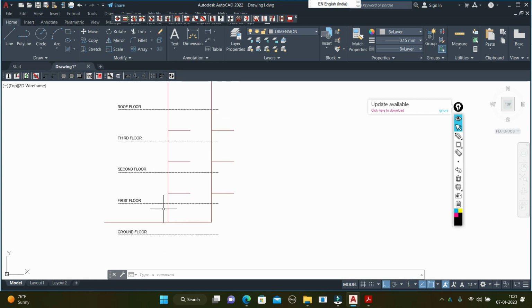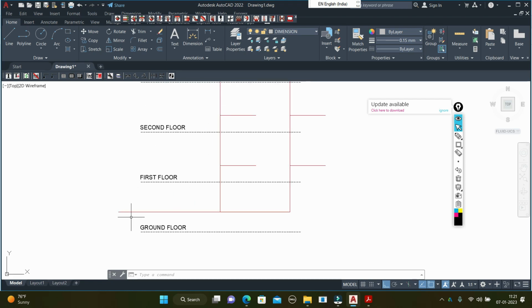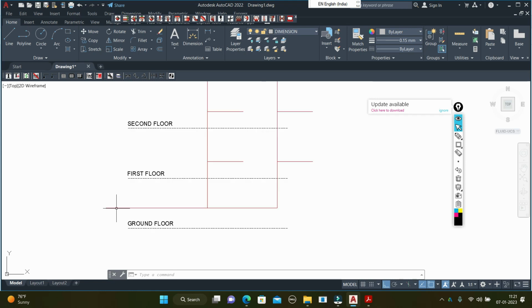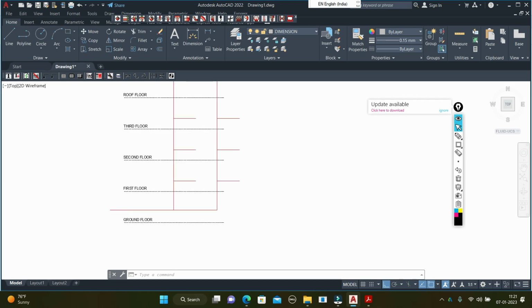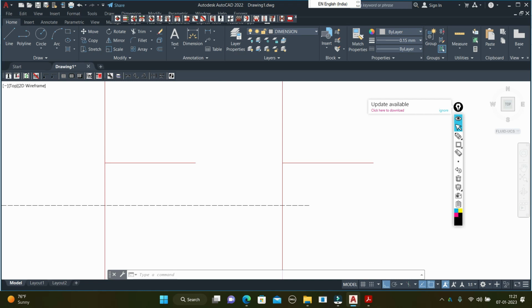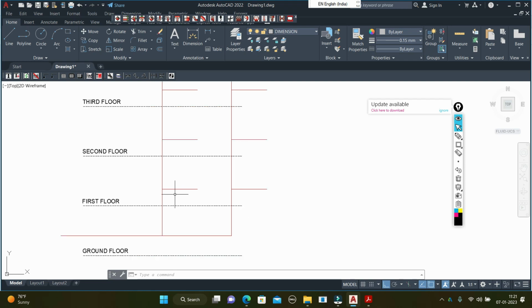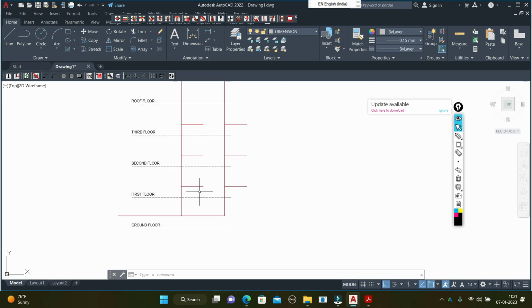So we already placed the pipe of the breaching inlet not less than 457 millimeter and not more than 1219 millimeter from the ground floor level, and also as per the NFPA the landing valve should not be less than 900 millimeter and more than 1200 millimeter. So already we placed as per the NFPA.